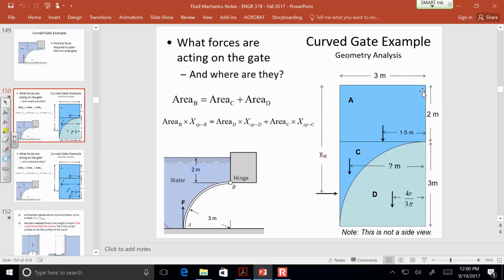So when you're finding all the forces, you treat everything like it's its own block. And then you just assume it's about the centroid, like for FA, you just assume it's in the dead middle. Yeah, it is, because the center of area for a rectangle, when we're thinking about its horizontal location, is halfway between the two edges. So since it's a symmetrical shape, the center of area, and therefore the center of that force, is halfway between the two edges. So then, like for the C shape, wherever that is, you just find the force of that shape. That's right.